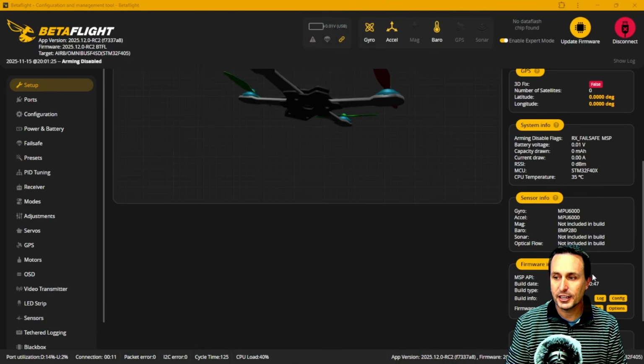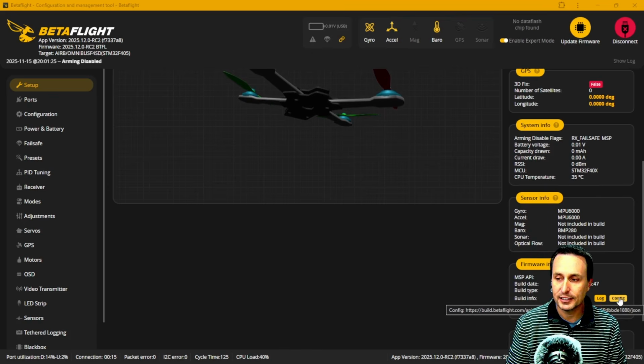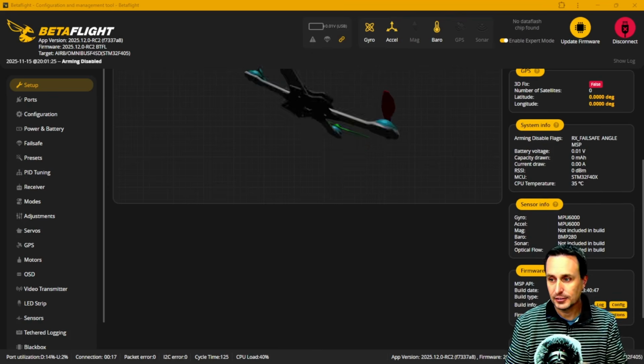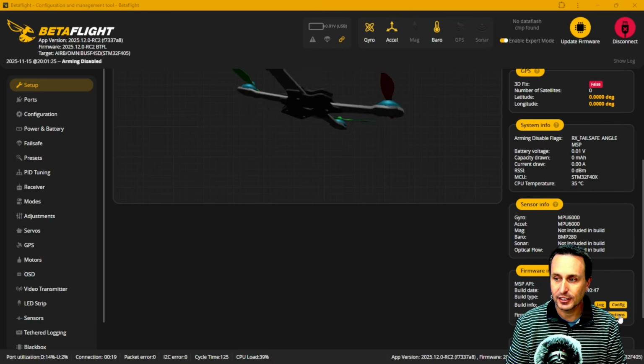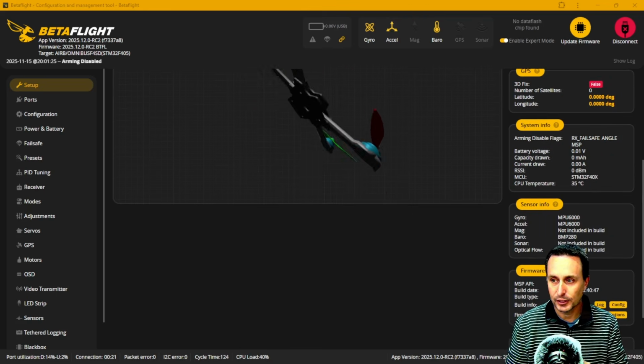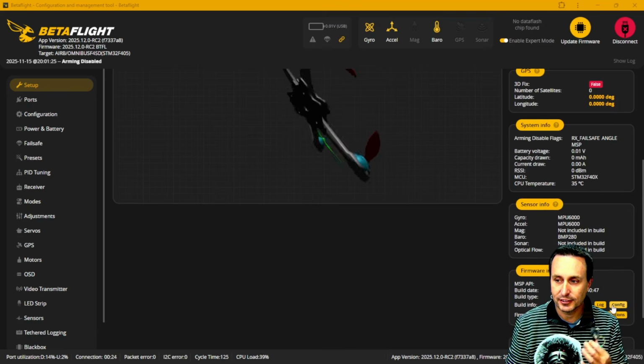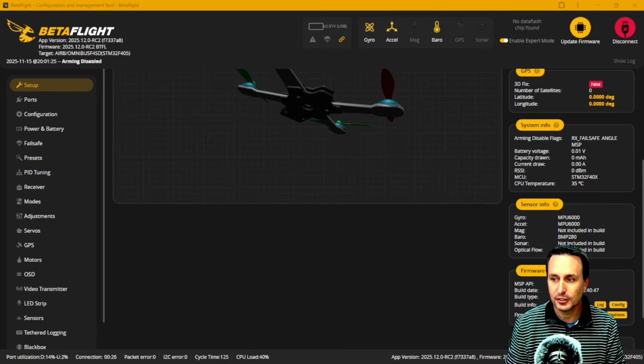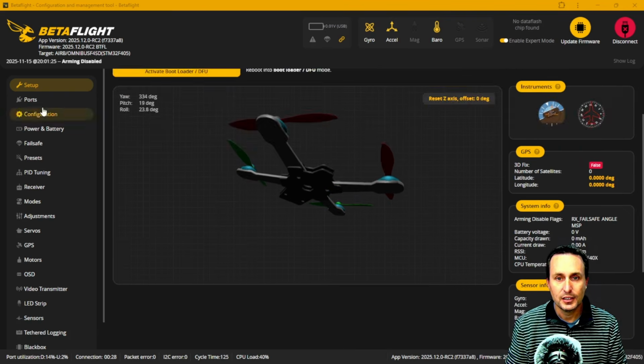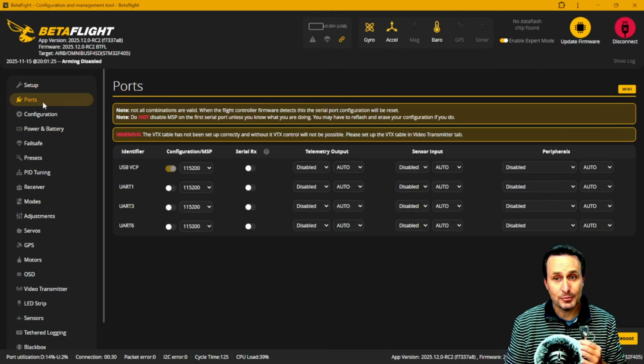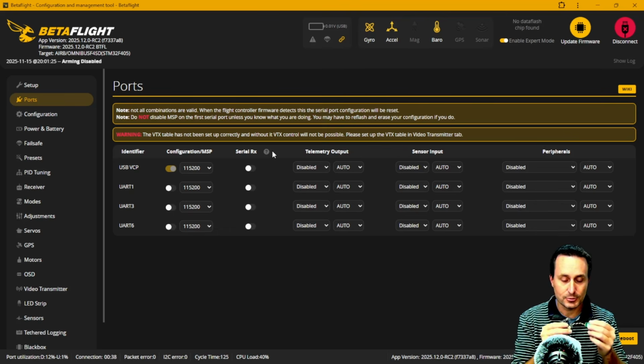You can always go down here and look in the config to see what parameters you had added to this. If you forget, like if you didn't select wing or something of that nature, or if you had PWM or D-shot, things of that nature, you can click on that down here, or in the options down here as well. So in here, what I recommend, the first thing you do is try to get your receiver working. So have a receiver. I'm not going to go through getting receivers set up. I have an Express LRS one on here.